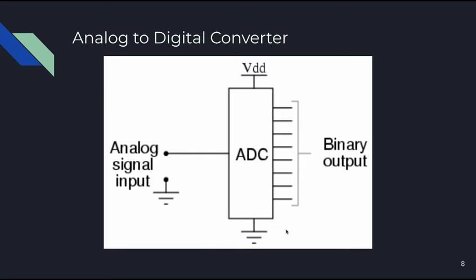Second, a finite time is involved in the process of converting an analog signal into a digital quantity, and this time can be critical in the control of fast processes where the accuracy of control depends upon the speed of the controlling computer. Degrading the speed of operation of the control computer by imposing a requirement for A to D conversion thus impairs the accuracy by which the process is controlled.